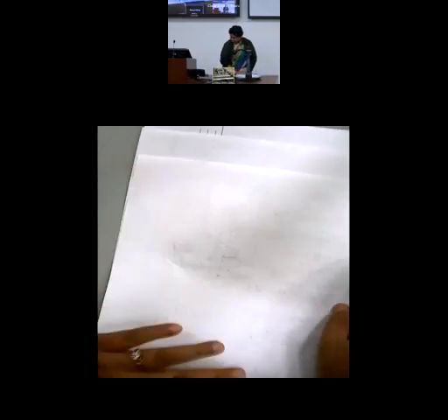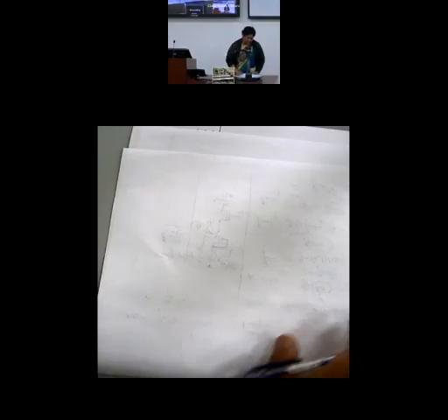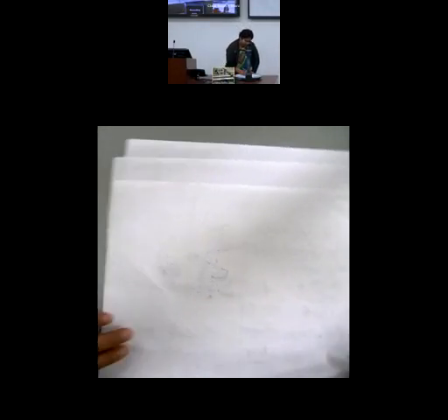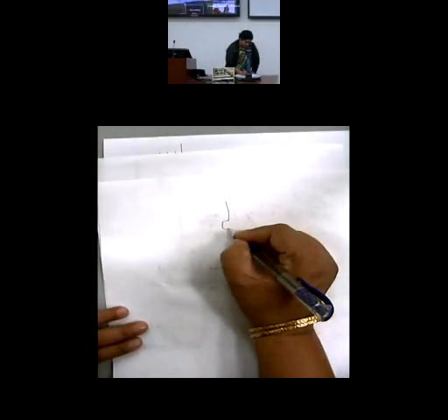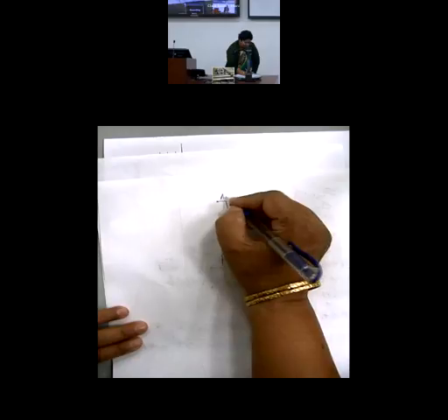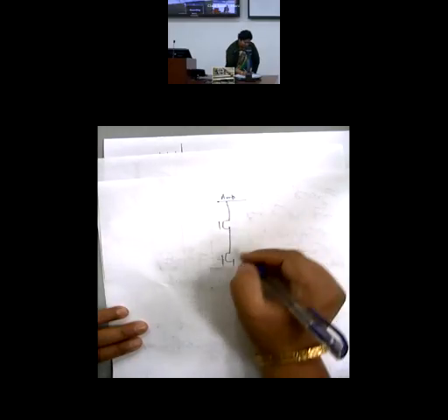So let us repeat what I did. Remember cascode. I'm using gain boosting. So I look at my last arm. So this is my cascode. Here you connect your differential amplifier or any other amplifier.